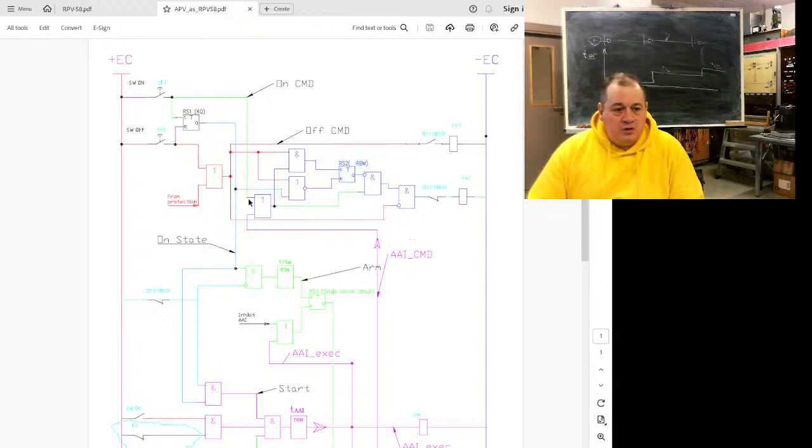We have the on command, we have the command to do auto reclosing. It will go this way. Here, this element prevents reclosing if a signal from protection or from manual disconnect exists. If protection keeps sending the signal do not connect, nothing will happen.